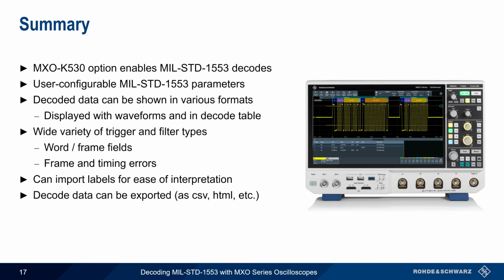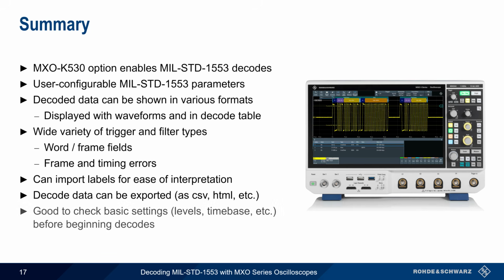Decoded serial data can also be exported as CSV, HTML, and a number of other formats. And finally, remember that it's a good idea to check basic oscilloscope settings, such as levels, thresholds, time base, etc., before starting decodes. This concludes our presentation, Decoding MIL-STD-1553 with MXO series oscilloscopes.